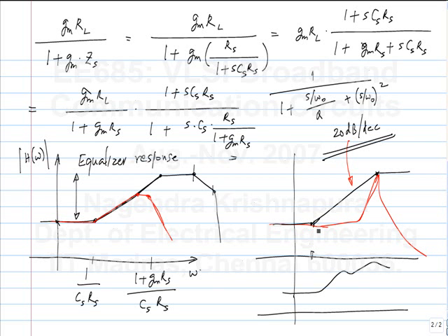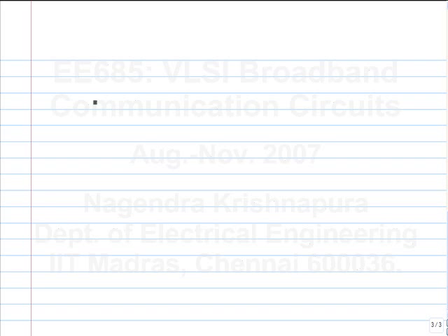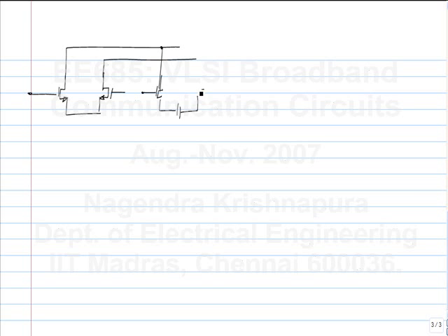So you can also do it with parallel paths. You take this and you can add a capacitively degenerated differential pair in parallel, both driven by the same inputs. So this part gives you the DC response and this part gives you the overshoot when you apply a step. So the combination will give you the steady state plus the overshoot. Okay. When it goes through a low pass channel, the overshoot becomes flattened because of the low pass response, and you get something closer to a nice step that you want.